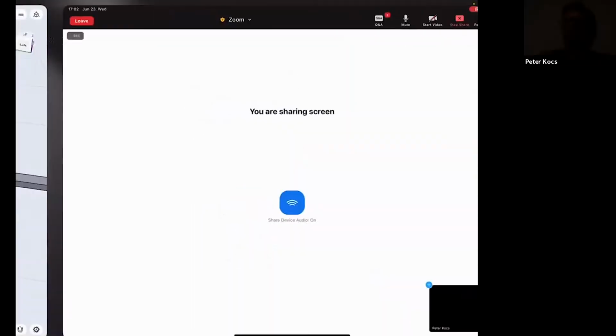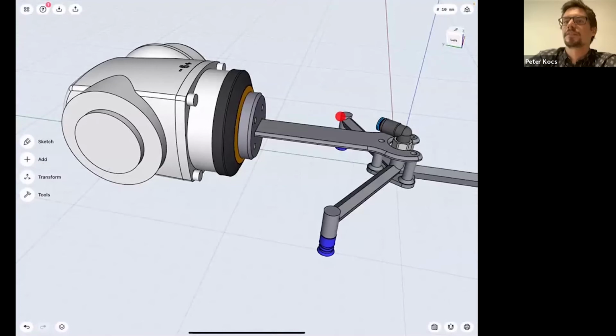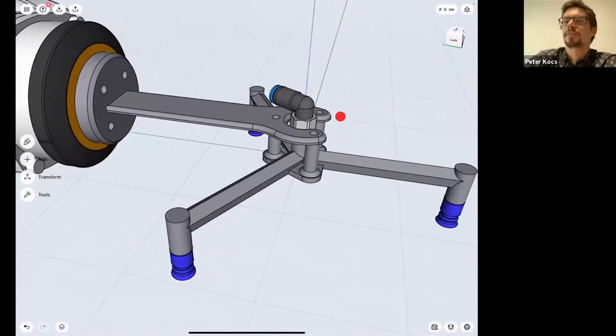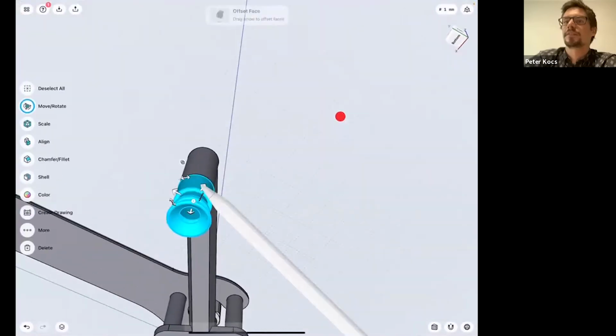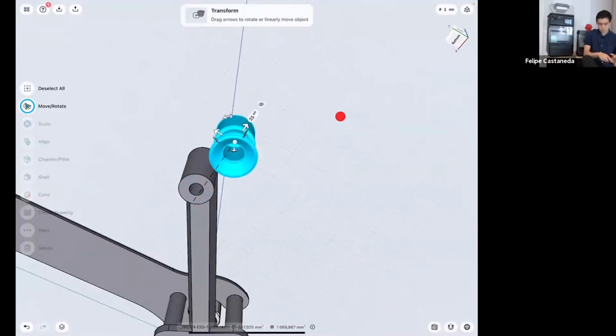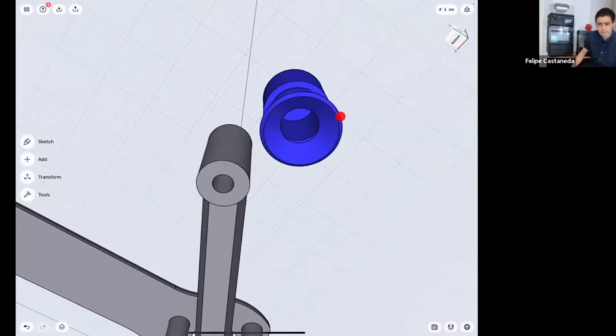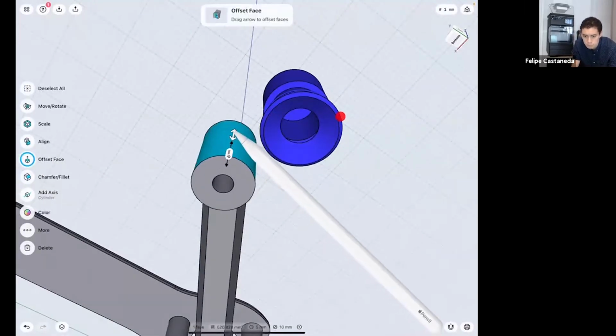For example, you defined it as 3 millimeters. If you wanted to make them bigger or smaller, how hard would that be? In this case, it would be easier to do in a step when the model is not ready yet. Let's say I'm going to move this body away, and I can redimension any circular face by grabbing the perimeter and moving it.